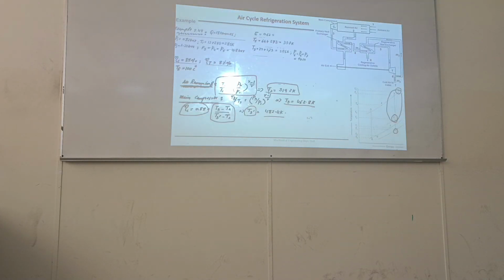Okay, so till this point, now we have calculated T3. Now what about T4? Here is that heat exchanger. For this heat exchanger, what was given? Effectiveness. And what is effectiveness? Actual heat transfer divided by maximum possible. So actual is MCP (T3 minus T4), this temperature change, divided by maximum possible, MCP (T3 minus T2).